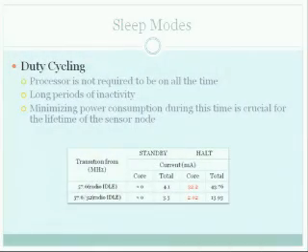In the standby mode, the clock oscillation is completely stopped. In the halt mode, what happens is that the clock is still running, but it's blocked from several components. Now, if you see, the current consumption in both cases is in terms of several milliamperes. So we're getting milliwatts of power consumption.